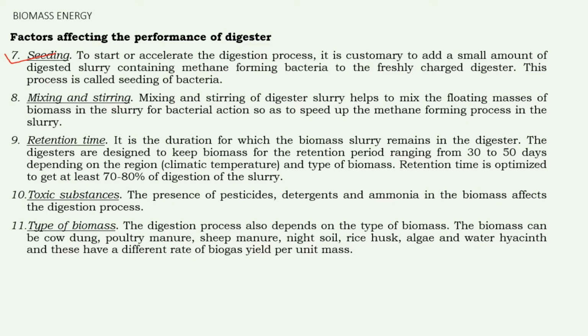As we discussed, methane forming bacteria work slowly, so we need to accelerate the reaction. Whatever digested slurry comes out, some part of that is added to the fresh slurry sent to the digester. This process we call seeding.